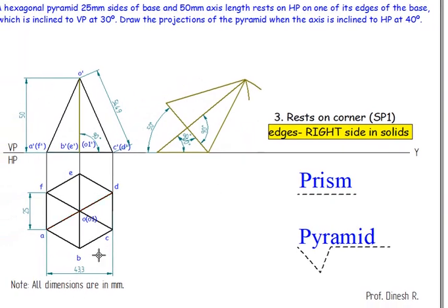this 43.3 length. So this angle I'm going to draw 50 degrees, 43.3. Then from here I'm going to take this length measurement. From here I'm going to cut it. I'm going to draw this triangle. After drawing it, I'll take this measurement from C dash to O1 dash and cut an arc. Then I'm going to draw it and extend.